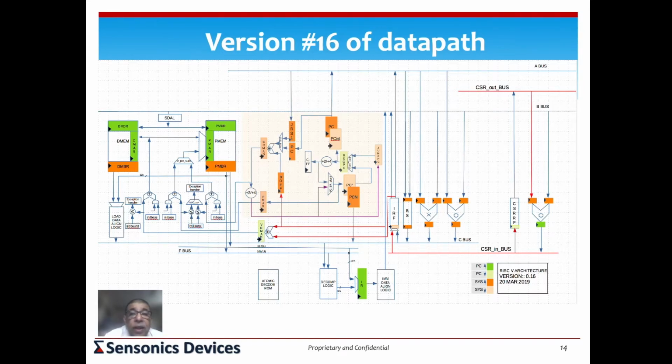So now, as you can see here, we have basically three parts in this data path. The extreme right part is what you would first form when you examine the instruction words. The instructions directly imply this right part of the data path. As you can see here, we define this as having three buses actually. One is the C bus, which is the destination bus. One is the A and the B bus, which are the two source operand buses.